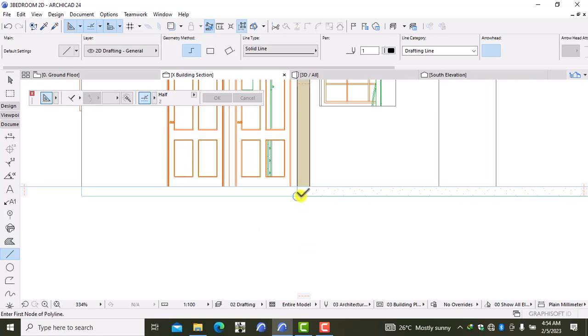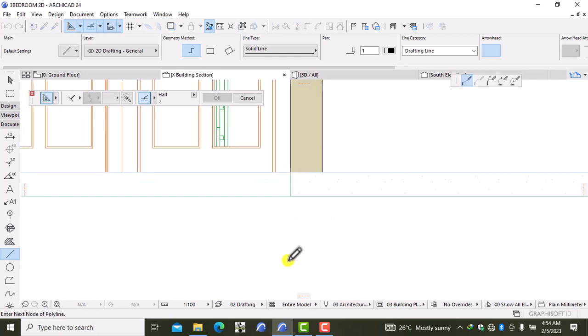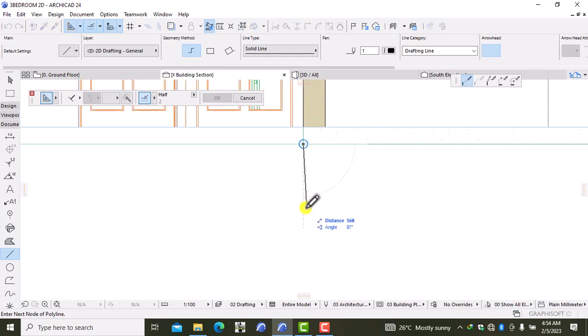I come to where the color is starting, to this end. So I'm drawing these wall footings, and remember on the section I'm going to indicate the height of the foundation to be determined at site. We don't specifically know the height of our footing, so we're just using an arbitrary value. I can decide to work with maybe 1000. Enter, and then the footing.